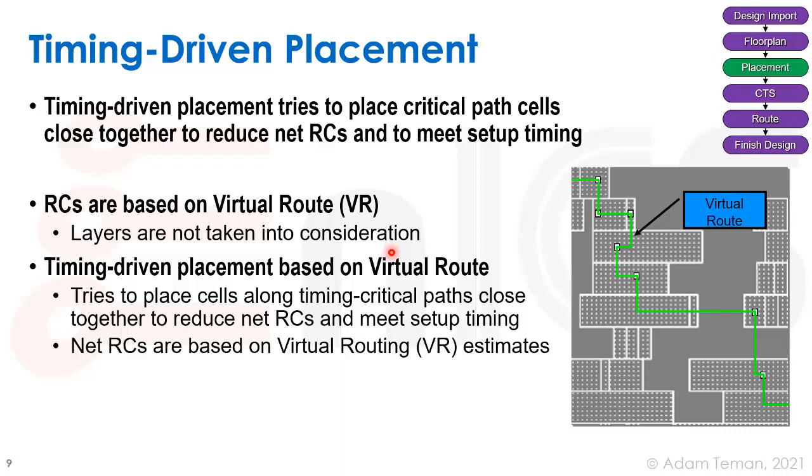And so we're not going to do what we call detailed routing, where we go and fix DRCs and so forth. What we're going to do is just a virtual route or a trial route. We're going to do a quick and sloppy route. We're not going to fix any DRCs, any shorts or opens. We're just going to see, if we took a wire that has to go to another cell, how it's going to go over there, and do it real quick and sloppy with one metal or something like that. And then we're going to extract the RC of it to get a good estimation.